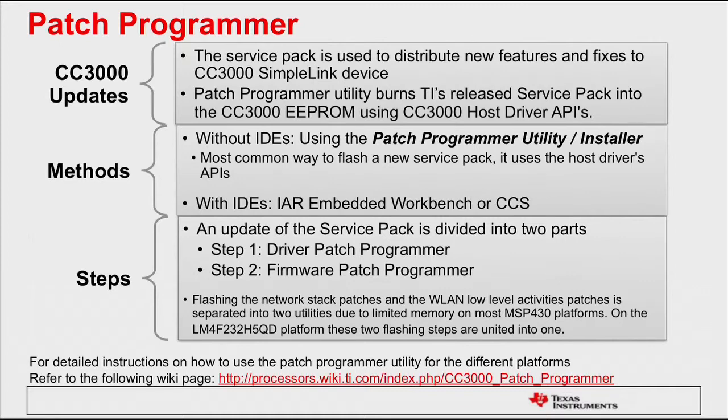Okay, let's talk about the patch programmer. So we talked a little bit before about the EEPROM, and there are patches on that if there are any system issues or bug fixes that are implemented. So let's talk about how the patch programmer fits into that. There are actually two methods to update that patch into the EEPROM itself. One is without an IDE, using the patch programmer utility. So TI has this available online for the different platforms that we support. And so it's very easy to use the patch programmer and download directly into the EEPROM itself.